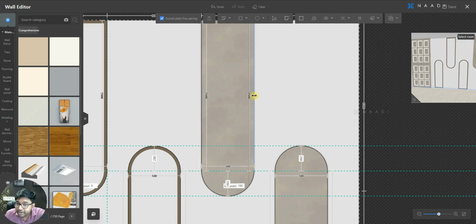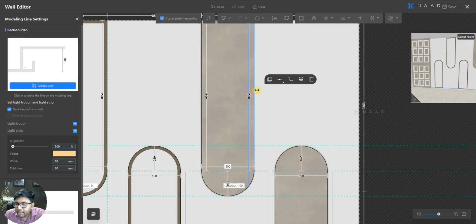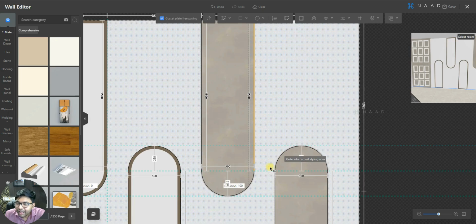And once it is added, just select that edge, and here in the floating window, can you see the duplicate option? Shortcut is Ctrl C, right? Just click it and just select your other edges. Can you see? The same Cove property will be applied for that selected edge too, right? So it is that simple.